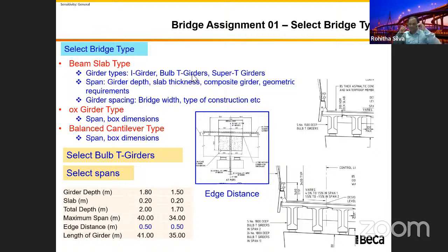One reason is safety, especially the constructability reason, because we are building this one in a valley. Sorry, I don't have a slide here. If you just go with the I girder, there is a gap after you erect it. When you are filling this gap, placing temporary formwork is really hard because the height of the valley is 23 meters maximum. It varies from about 9 meters to 23 and again to 5-6 meters on the abutment B side. Because of that, it's too risky and too costly.